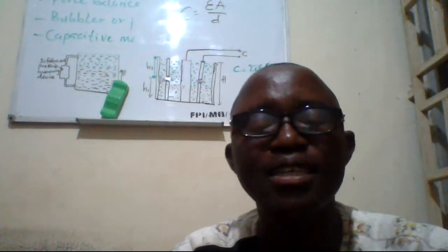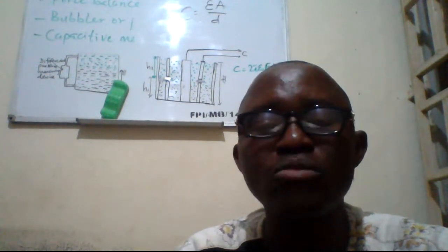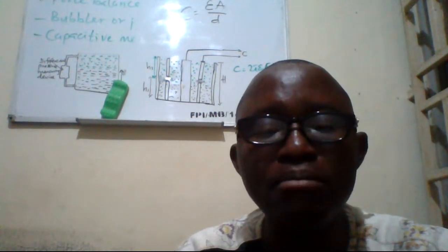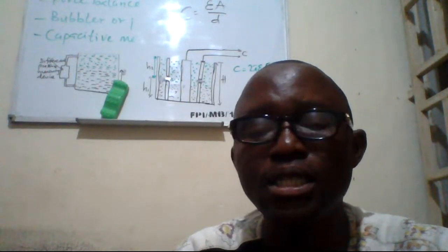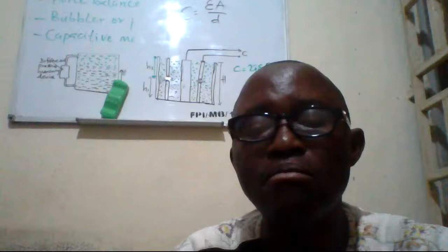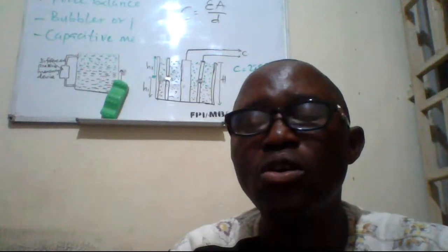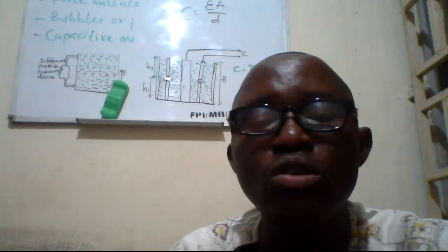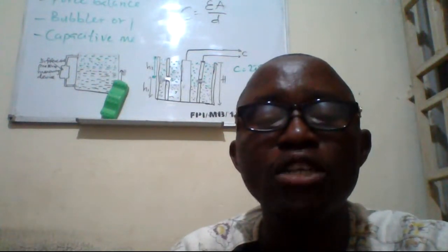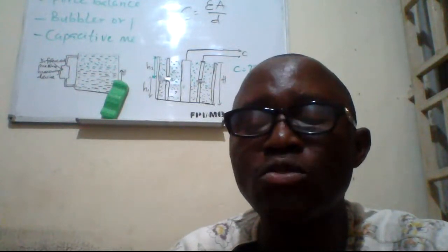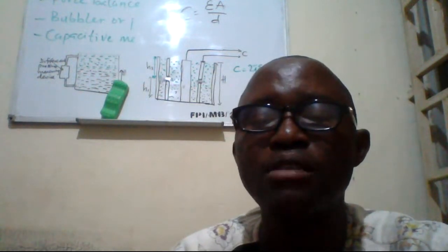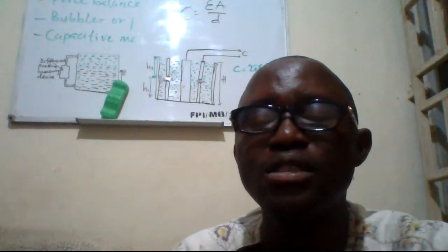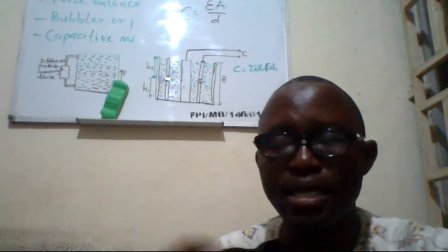So now I think we have come to the discussion of the third system, which is the capacitive level measurement. There is a calculation based on the formula that we just encountered, whereby we can calculate the level of liquid in a very tall tank containing a particular liquid with a particular permittivity, and the vapor having a different permittivity inside the tank.